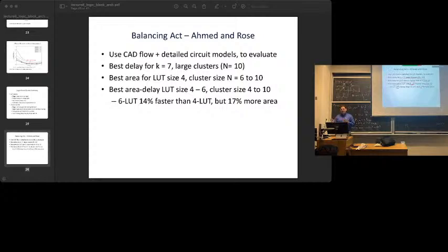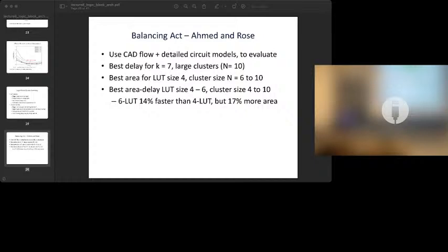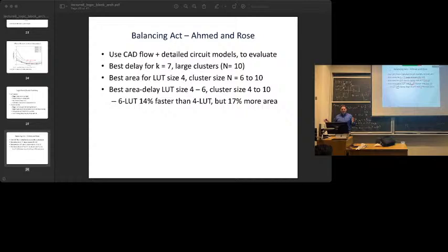Instead, we just say for every benchmark, we'll make an FPGA that is basically the right size for it. It's like we make a square grid that just barely fits that design. The reason is you get less round off. If you were to say I only have 5 FPGAs, you might have a lot of designs where they go from using 83% of the FPGA to using 76%, but they still have to use that FPGA. That just adds noise to your experiments. So when you're doing architecture studies, you usually neglect that.